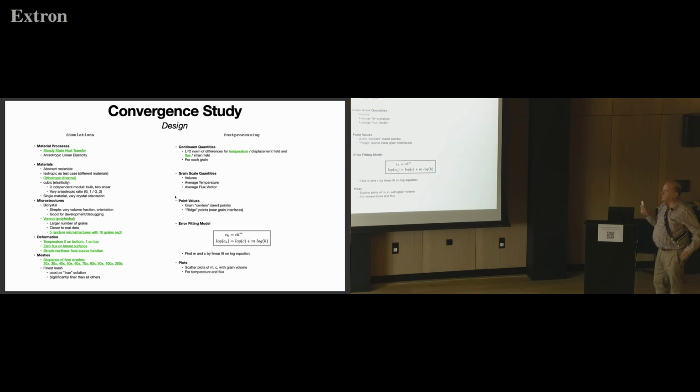Now the deformation, there's really just one simple deformation. It sort of made my brain hurt to think of an analytic solution that I want to use for all these. So I just decided to use the finest mesh, and because I'm using the finest mesh as the true solution, I made it a sequence of 10 different meshes that we'll solve on. So we'll get a good fit, and hopefully that'll take care of that.